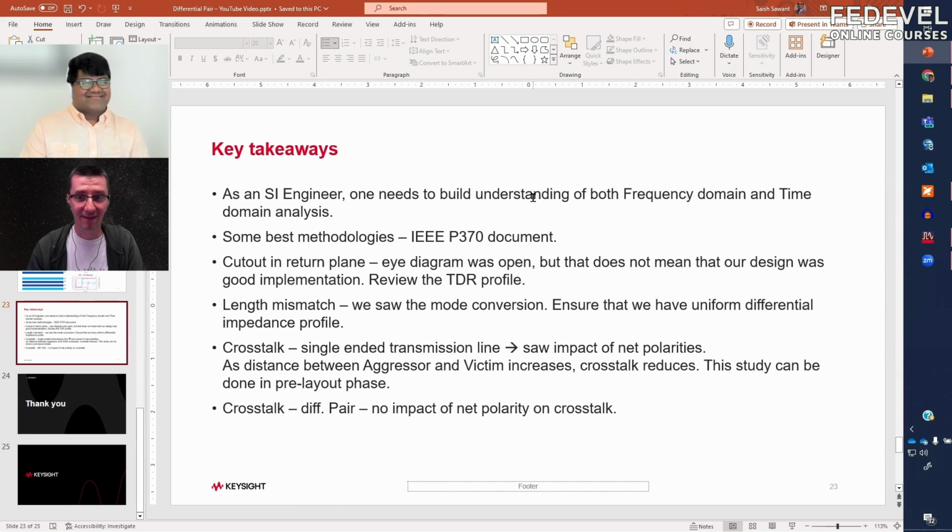But then I found out that even if everything looks correct in your scope, the problem is you see the results on your scope only for this specific signal running at this specific frequency. And if, for example, the frequency of your signal changes, you don't see this result. It doesn't mean the signal will still be the same quality.